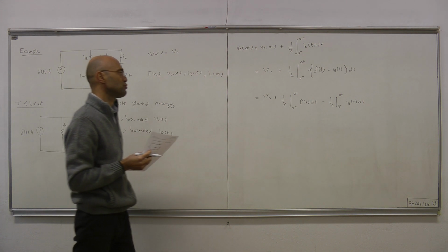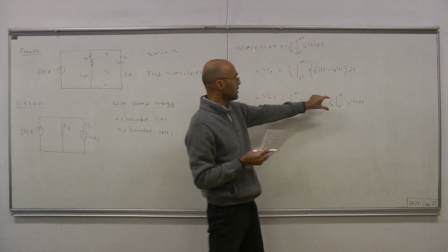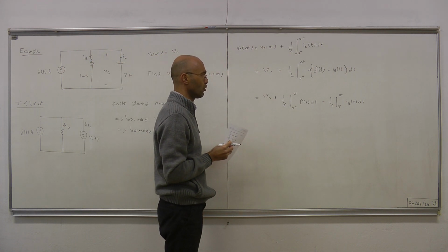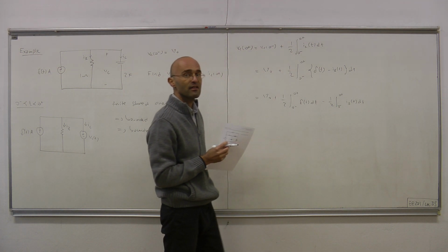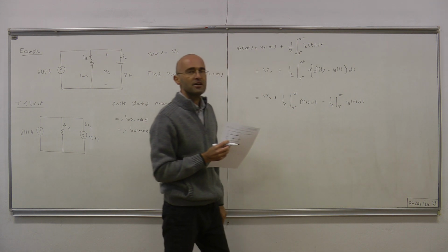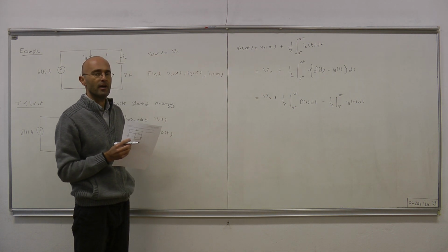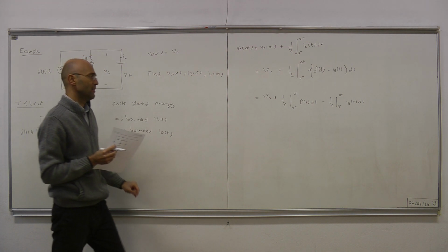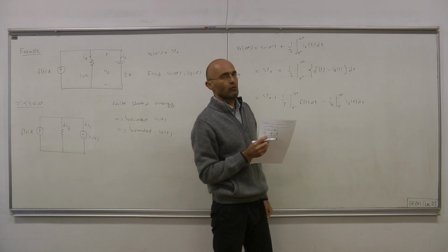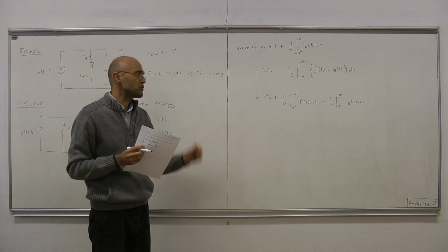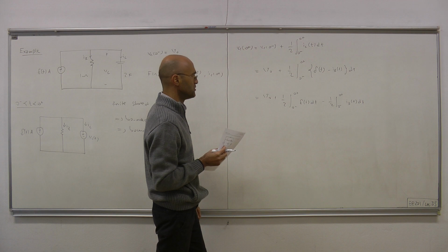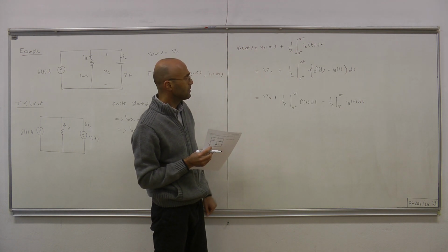But because we're performing the integration throughout a very special interval, an interval of infinitesimally small length, we don't have to know exactly what iR(t) is. All we have to know is whether it's bounded or not. And we do know that it's bounded. Therefore, you integrate a bounded signal in this interval from 0- to 0+, which has arbitrarily small length, and this is negligible. Therefore we can replace it with 0.